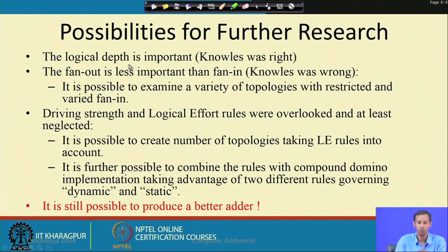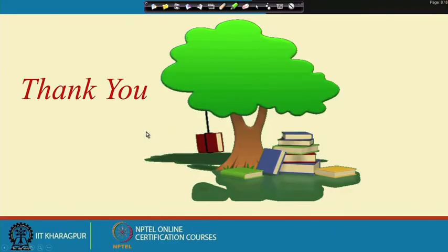So, considering these adders, we can take different combinations of this prefix addition. What will be the optimized combination so that I can get a minimized number of dot and semi dot operations, along with the logic depth being on the reduced or lower side? If we can optimize both things, obviously I will get one very good adder architecture. So, this is the end of this adder architecture.